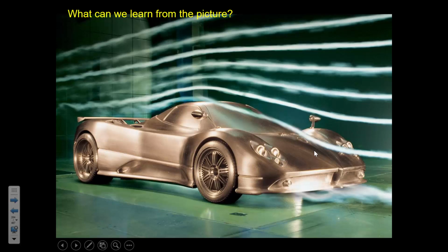acting upward. So here in this picture, to get this car back to a wing, you may be saying, well, this is a car, not a wing. But look at the cross-sectional shape of this vehicle. It's flat under the vehicle, and the rounded shape along the top kind of in some ways resembles a wing. So unintentionally, vehicles can produce lift, and at high speeds, that's not great for traction.